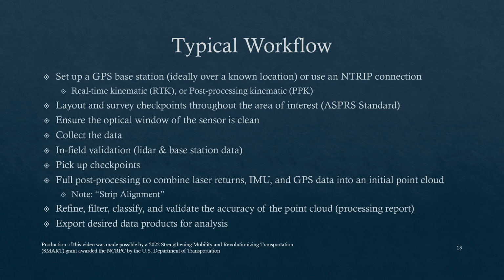Ensure the optical window of the sensor is clean, another critical component of this type of mapping mission. You want to follow the manufacturer's recommendations for cleaning that window. Be very careful doing that. Collect the data, in-field validation, always important. Picking up your checkpoints, and then post-processing.